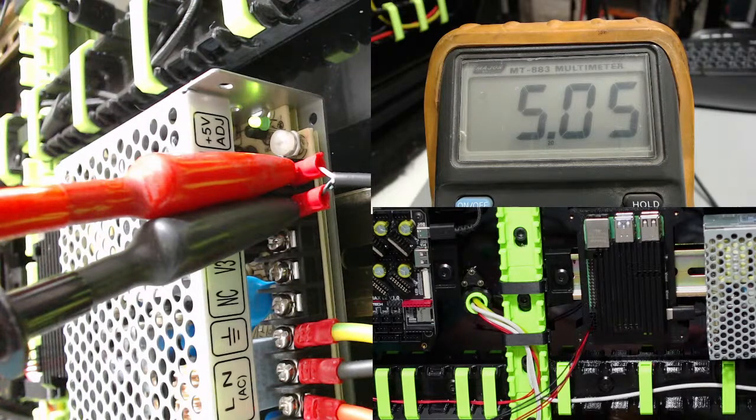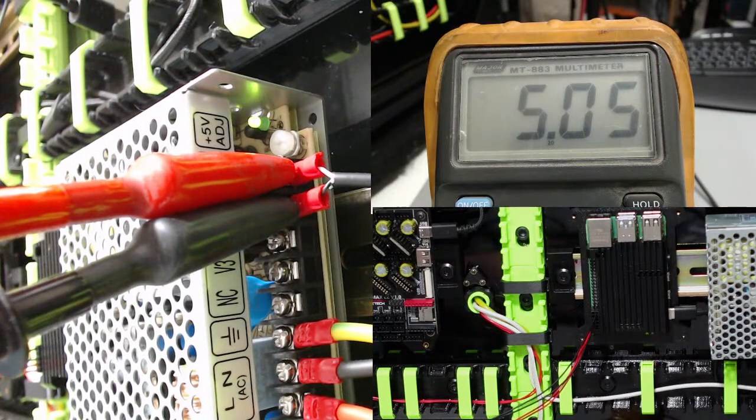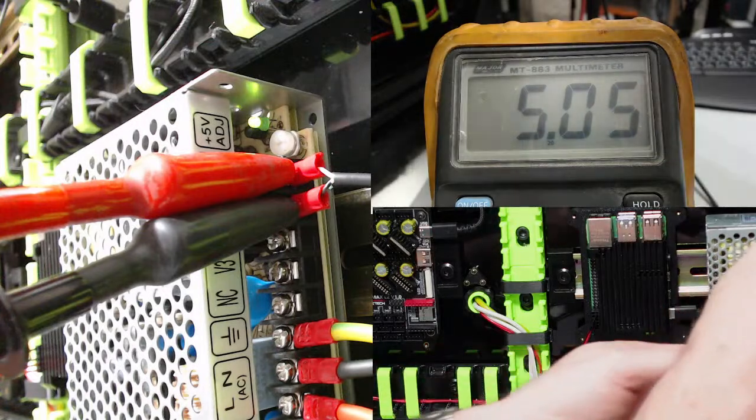So on the power supply, you will now see 5.05 volts, which is already slightly under. Now, if you buy a Raspberry Pi charger, specifically one for the Raspberry Pi 4, you will notice that the voltage is about 5.12, give or take. By buying your own power supply, you've got to be careful that you're not under voltage. But now let's go to the Raspberry Pi itself, right?